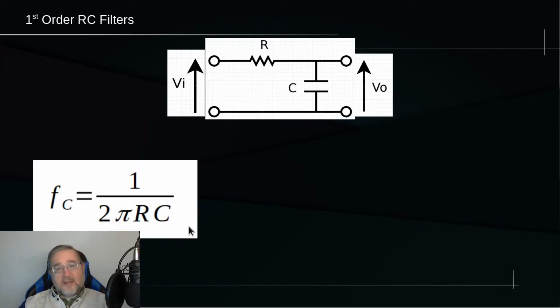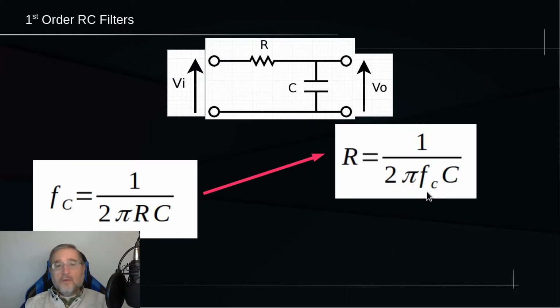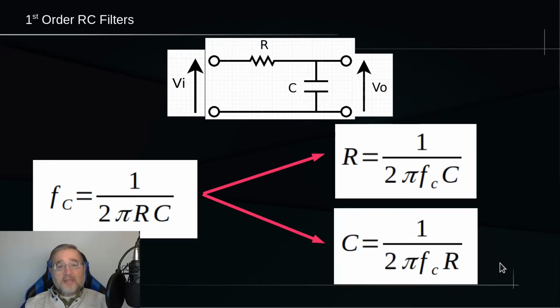It tells us, basically, that the cutoff frequency depends on both the resistance and the capacitance of the component making the circuit. The greater the resistance and the capacitance, the lower will be the cutoff frequency. Readjusting this formula, we can derive the one that allows us to calculate the resistance of the circuit and the one that will allow us to calculate the capacitance. Both formulas are the ones used for the design of the filter.